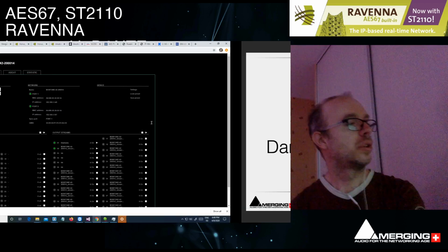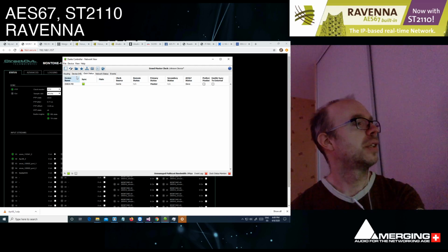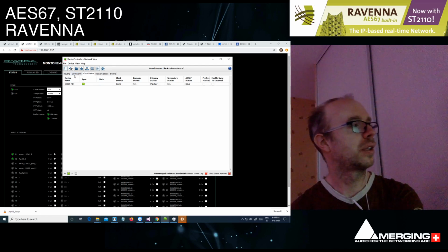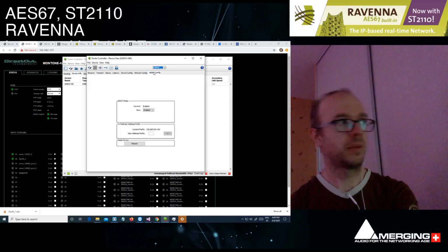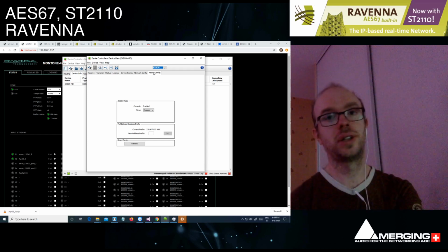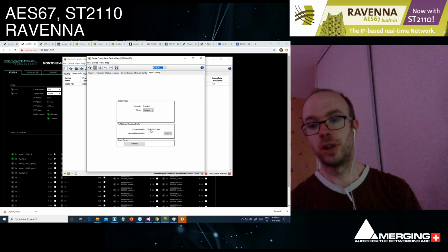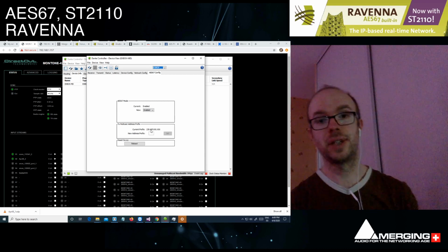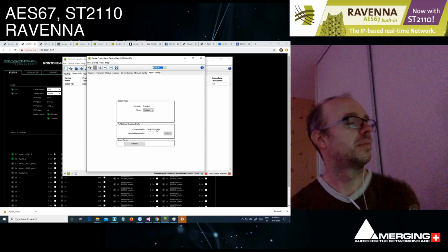So let's see how it works with Dante. With Dante, there are a few tricks to know. The first thing is that my Dante is properly configured to the right clock. So I will go to my device and go to the AES67 config tab. If you have a Dante device and it can do AES67, it will have this tab. If it doesn't, or the firmware is not updated, it doesn't have this tab at all. You have to enable it, and you have to choose a multicast prefix so that your Dante AES67 multicast addresses are constrained in a multicast subnet. It's a weird choice from Dante, but whatever. You have to know it: it's 67.